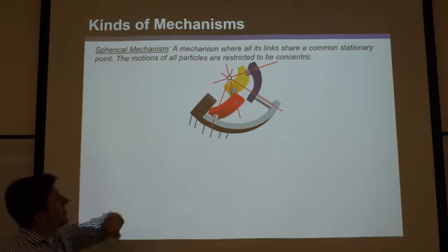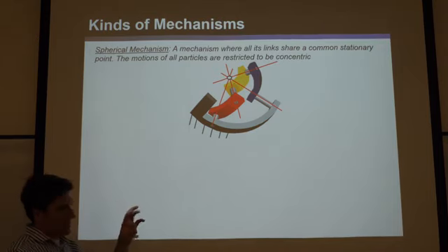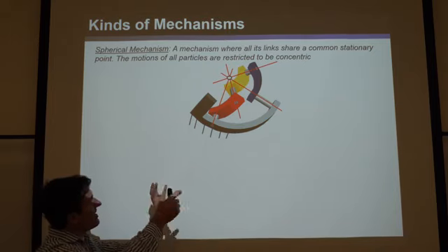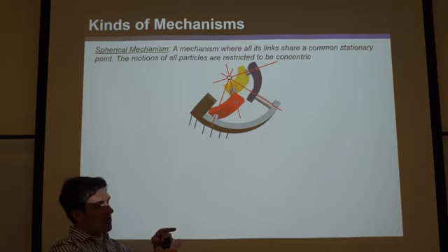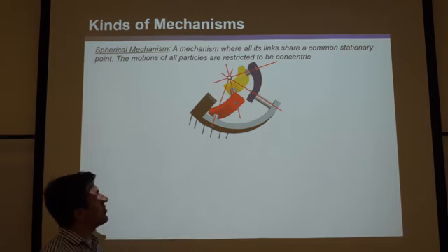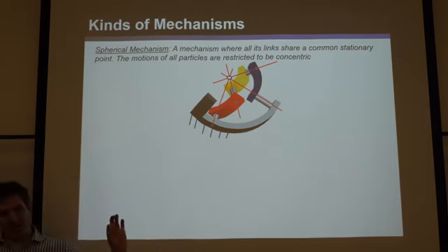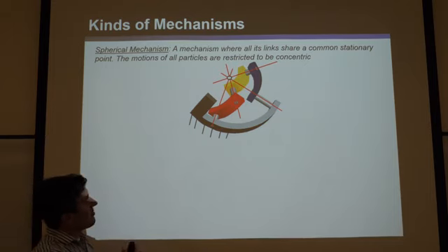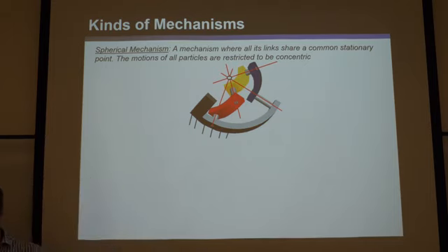You see that circled black outline dot that's white inside. That's where they all intersect. And no matter how those move, if you can visualize those red, yellow, and blue links rotating, those red axes may move, but they'll always intersect at the same point. And that point consequently won't move with respect to any of those other bodies. So if that point was a point on the yellow one, the blue one, or the red one, that point wouldn't move no matter how much the mechanism moves.